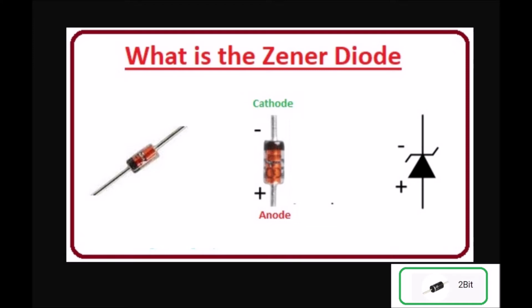Both breakdown types are present in Zener diodes, with the Zener effect predominating at lower voltages and avalanche breakdown at higher voltages. Zener diodes are widely used in electronic equipment of all kinds and are one of the basic building blocks of electronic circuits. They are used to generate low-power stabilized supply rails from a higher voltage and to provide reference voltages for circuits, especially stabilized power supplies. They are also used to protect circuits from overvoltage, especially electrostatic discharge, ESD.